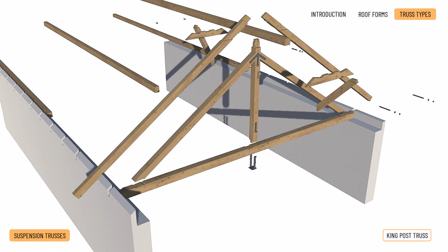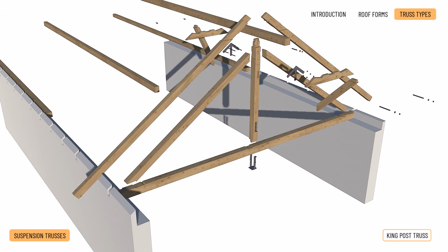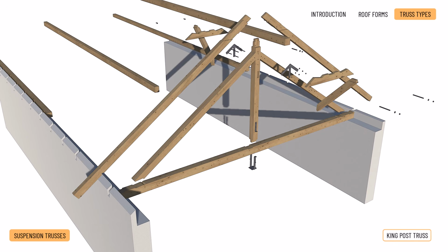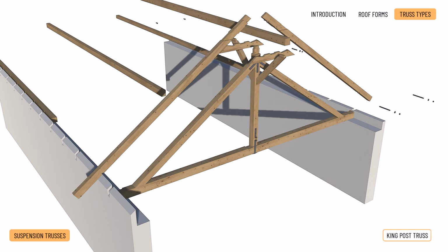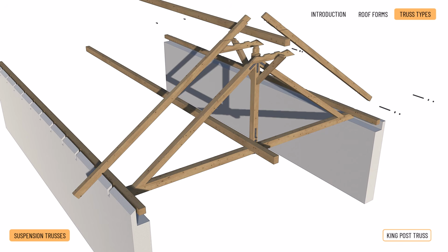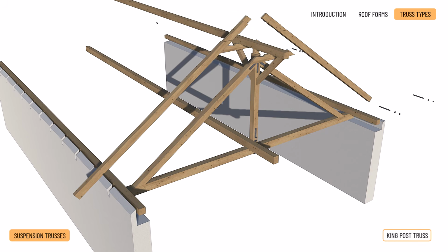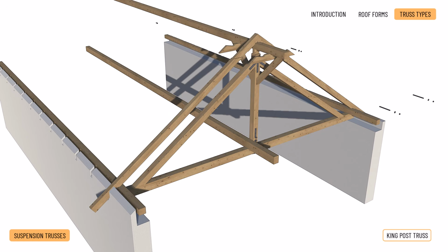The suspension system is completed by inclined struts, acting as a compressed beam, which connect to the suspension posts using double-notched housing joints, reinforced by steel straps. The inclined struts transfer loads onto the tie beams near the supports, where they are connected with double-notched housing joints. In addition to the top plate and the ridge beam, the entire structure is also reinforced longitudinally with a principal joist connected to the tie beams in the principal truss with single notches.